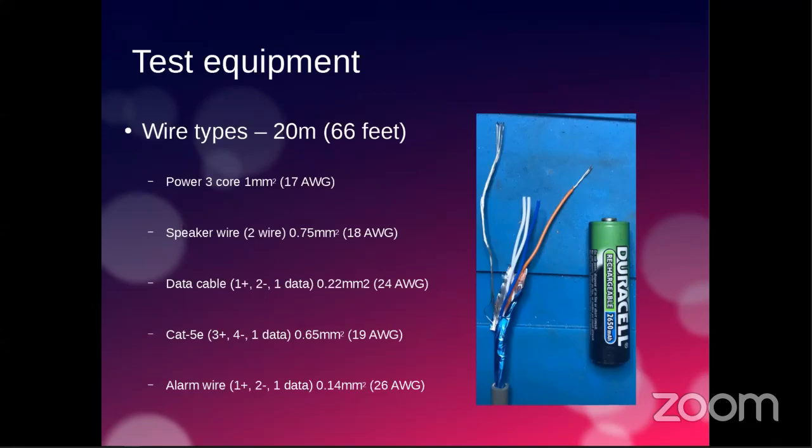I looked, Keith, I was going to change them all out, but the receiver boards don't have any resistors on them. I imagine they do, but they're probably surface mount. Yes, and they may well be 33. Dave may have changed. The ones on the receiver are 120 to match the 485 coming out of it. 120. Yeah, but that's the reception of the 485. It's more interesting. What are the resistors going into the data pins on the greenies? Right. Yeah, and don't forget there's a bunch of generic receivers as well that are not Dave's.